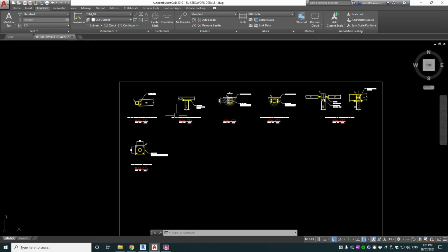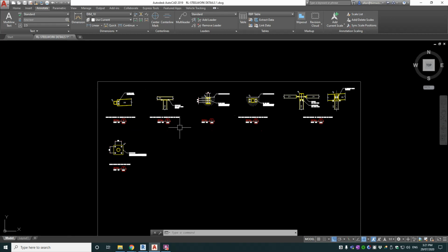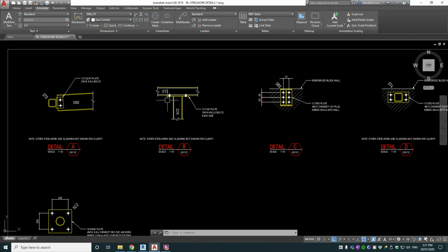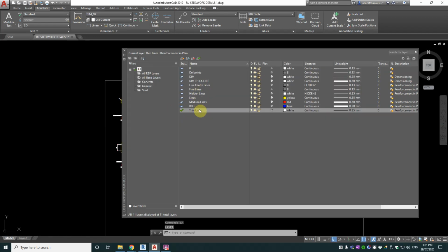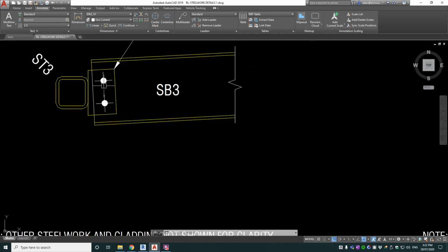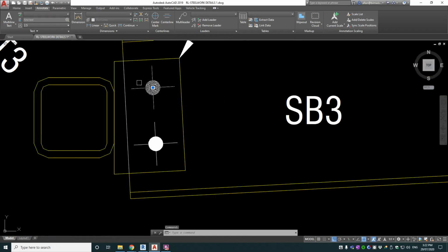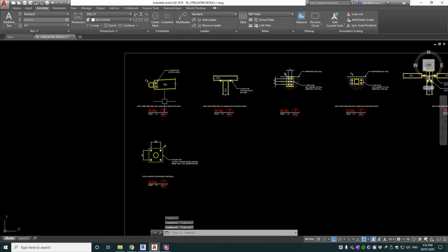Now just a couple of things to note, that we have done a couple of tricks to make this work in Revit. So first of all, we have the layers. Now the layers have a line weight on them, and that line weight is recognized in Revit. It's also important to have layers because you can control things in Revit with those layers, like the line type and the color if you needed color, etc. Couple other things to bear in mind is that some objects don't come into Revit too well. I don't use polylines, that's actually a block there.